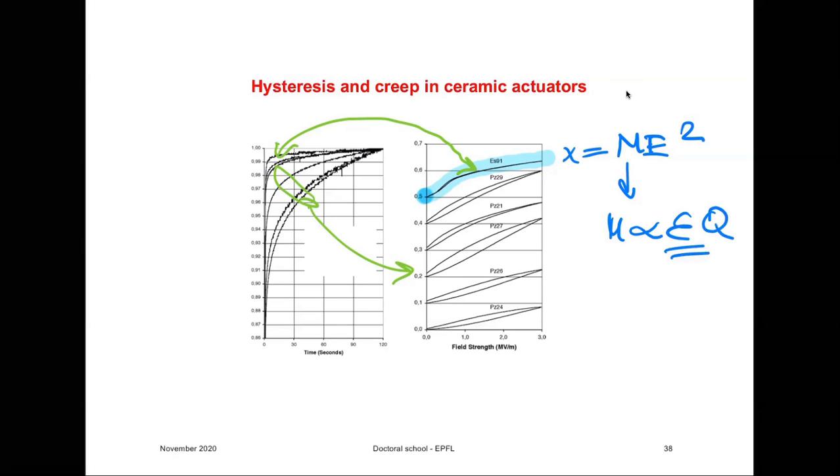Now, they don't have ferroelectric domains to give you hysteresis, but they do have internal nano-size objects, which are called polar nanoregions. Those also move under external field, but the hysteresis is much, much smaller than in ferroelectric materials. So you can get almost non-hysteretic and almost creep-free behavior.